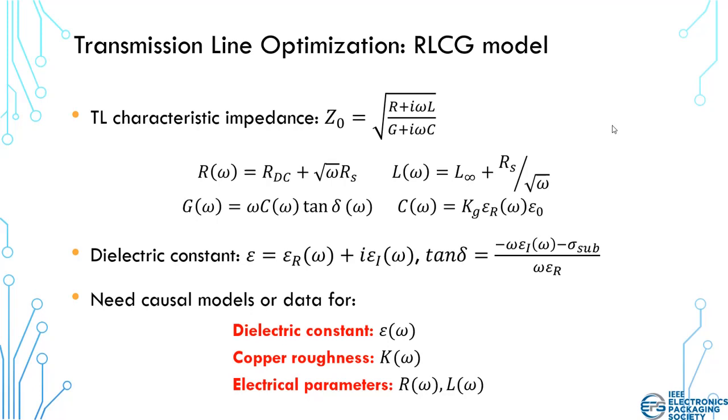Normally, if you look at the transmission line theory, the resistance just accounts for DC resistance, but real channels, including the specifications within 802.3 standards, specify accounting for skin resistance. They don't state this explicitly, but that's basically what you're accounting for, is the skin resistance of your channel. Then we have dielectric losses, that's the G term.